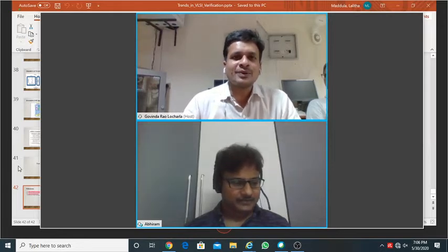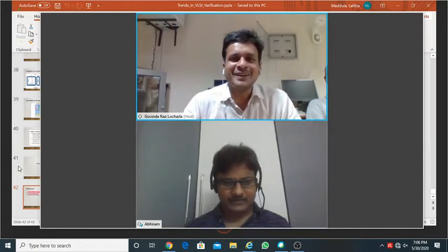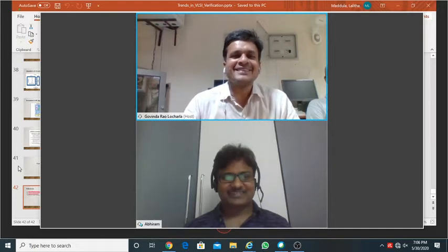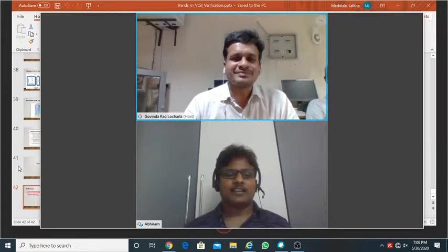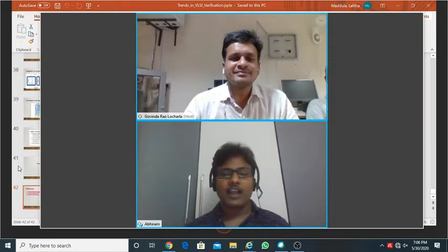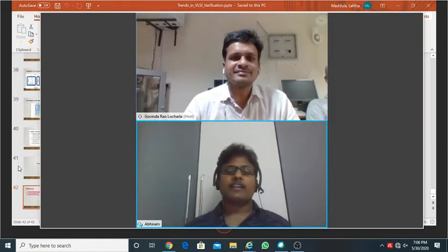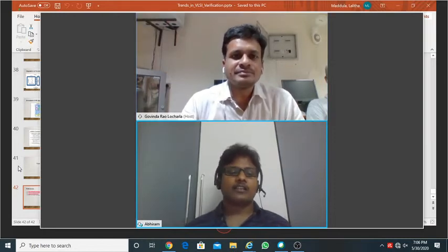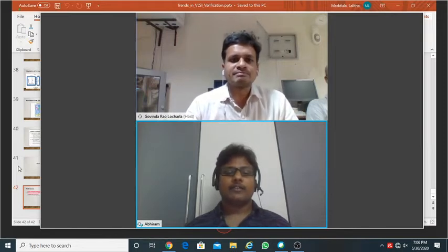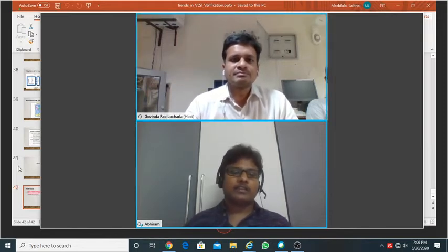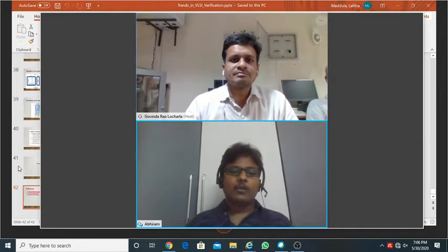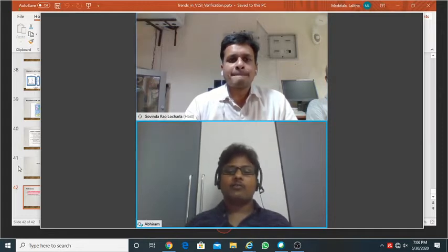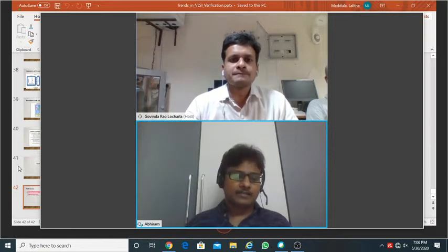Yeah. What is a test chip? Of course, it is also post-silicon. Basically, a test chip is, as the name suggests, a chip which is just used for testing. Especially used when we are going into newer nodes. Like if you're going from 7 nanometer to 5 nanometer, you don't know what challenges you will face, how much the yield is and all those things. So for those reasons, they put a test chip.